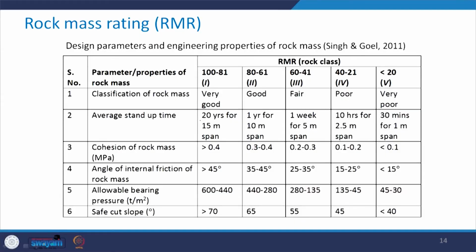See here, as I explained, it is 20 years for 15 meter span. It should not be that we wait for 5 years to provide the support system because the stand up time is this large. No, as soon as we excavate and it is convenient, convenient in the sense from the point of view of the construction activity, immediately we should provide the necessary support system.